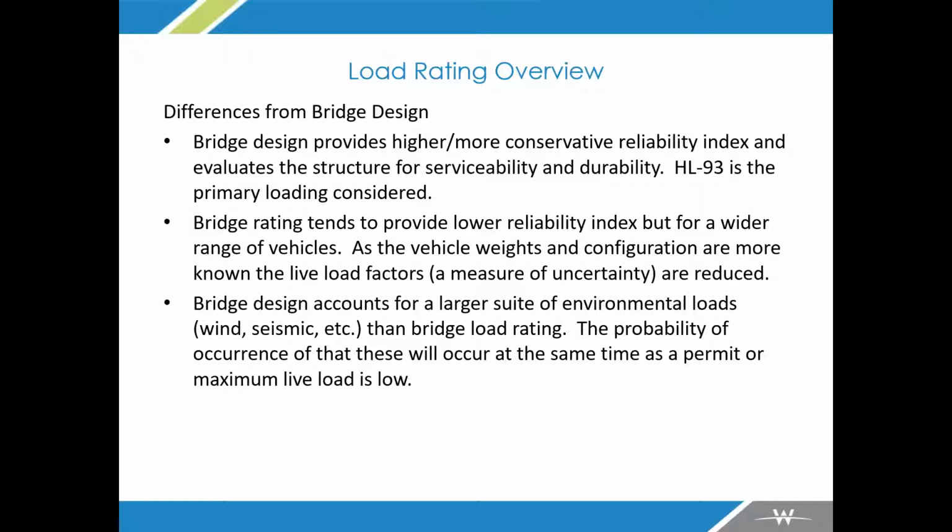There are some differences when we're looking at a load rating from what we do in bridge design. Not a huge difference here, but you're mostly just, again, comparing capacity to demand. But there's a little bit different treatment of some of these. There's a more conservative reliability index in design. What I mean by that is that you're usually looking at something like 1.75 for your live load factor, whereas when you get into operating rating factors you're lower on your load factor.